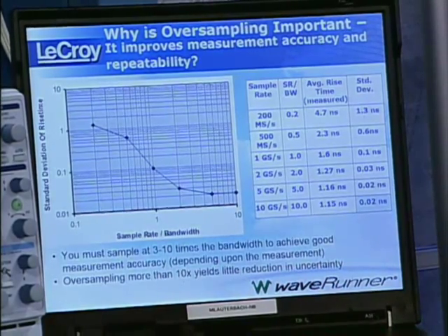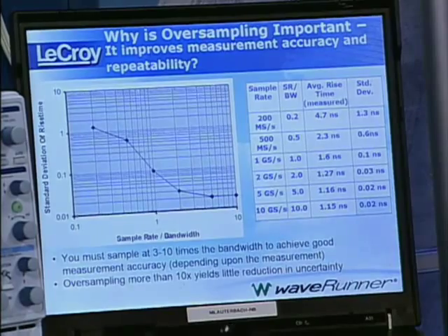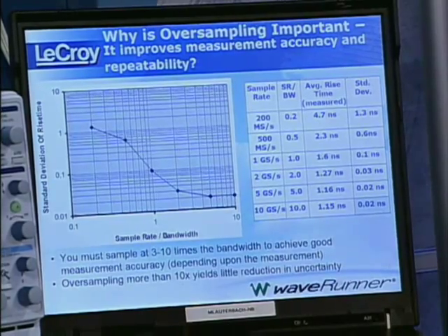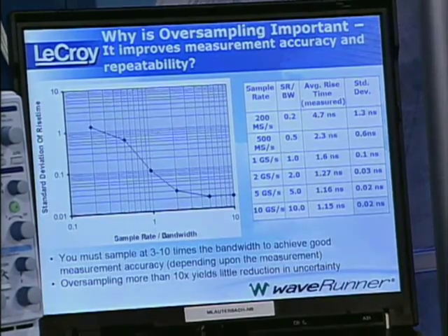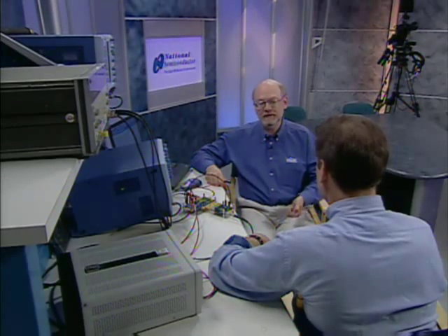So this would be why even your 350 megahertz bandwidth scope has gigasamples. Exactly. It has a 2.5 gigasample ADC. So the ratio of the ADC sampling rate to the bandwidth is good. That's critical for us because we publish this. It goes into a legal document, our data sheet. Right, so there's no question about the quality of our measurements. If you want to characterize a part, you want to know for sure that the numbers you're putting down there are right, whether that's a published data sheet or something that you merely give to your boss, saying, boss, here's the part that we've made. Right. So you want to have confidence in your measurements.